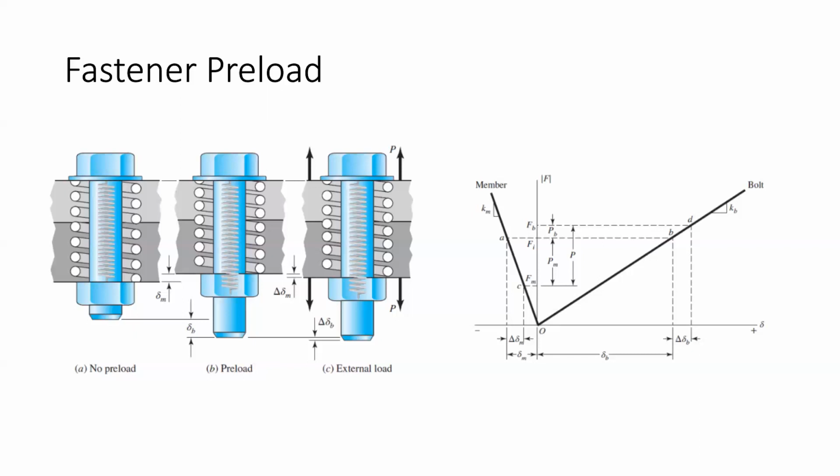A really common pitfall is, oh, I'll just throw a fastener in between and put a nut on the other side, and it will prevent these two plates from sliding, right? As we talked about in materials last week, the shear strength of materials is typically a lot weaker than the normal strength or the tensile strength. So in this case, it's bad because you're shearing the fastener. And the first piece of advice you ever hear when designing with fasteners is, don't shear the fastener. And that's correct. You don't want to be loading these relatively thin interfaces in shear.